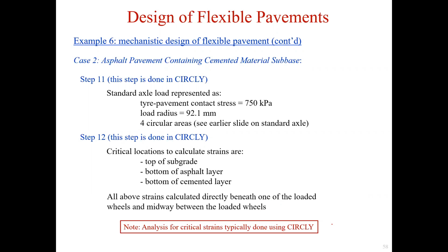Same as case 1, step 11 is to assume approximate standard axle loading. Step 12 is to determine 3 critical locations to calculate strength from the software CIRCLY, both directly beneath one of the loaded wheels and midway between the loaded wheels.